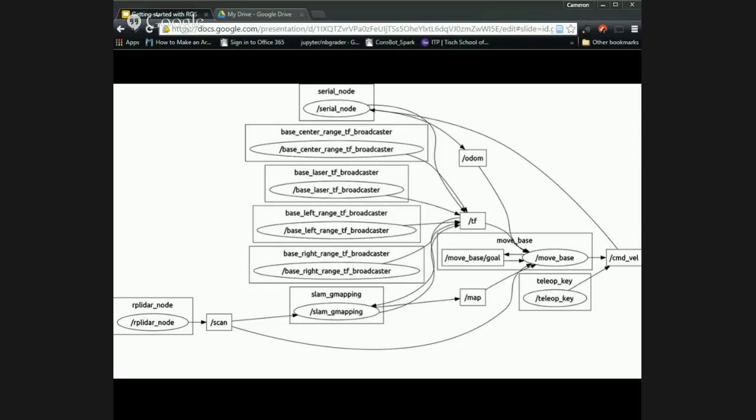Next, we talked about ROS Core, the name server that ties everything together and allows you to run ROS across multiple systems. Then we talked about ROS nodes. Those are the atomic units of how ROS works. They're the sub-applications of all of your computation. Any chunk of code that does computation, you should typically put in its own ROS node.